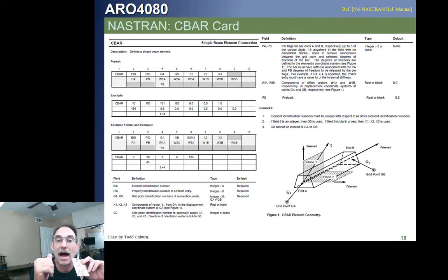So normally we talk about the moment of inertia of a section about its x-axis. Well, what this will do is this will define bending in the plane. So plane 1 is this vertical plane. So if we call out grid point 1, 2, and some point directly above it like this, normal to it, then this plane 1 bending, the first bending moment and the shear will be in this plane, and the bending moment 1 will be in this plane, and bending moment 2 will be in this plane, and shear 2 will be in this plane, okay?